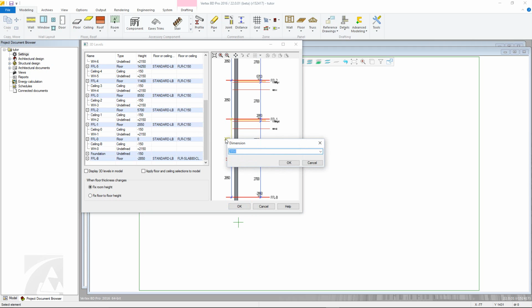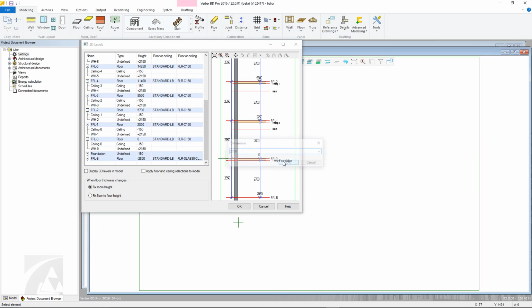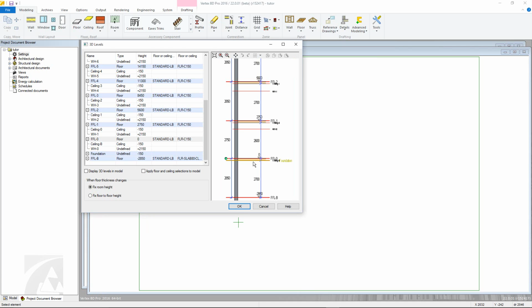So for example, if I double-click this ground floor wall height value, I can then enter in a new value. And as soon as I click OK, the Preview panel updates, altering the height of the building above, as well as changing the finished floor level of the first story. Window header heights also work in the same way.